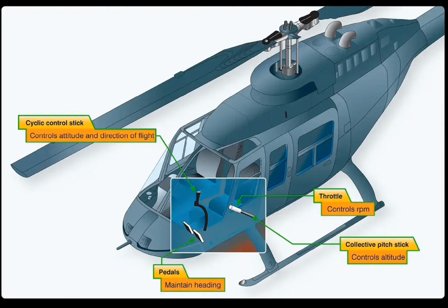Cockpit adjustable tab, attached to the trailing edge of a primary control, moves opposite the direction of the control surface. Balance tab also moves in the opposite direction of the control surface, but it is not adjustable from the cockpit, it is a fixed linkage.